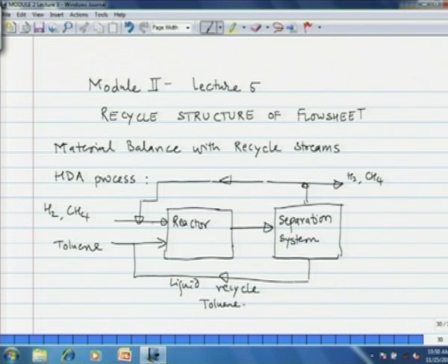Let Ft denote the total toluene feed to the reactor, out of which some part comes as a recycle stream and other as fresh stream. So, the fresh toluene that is fed to the reactor is denoted by FFT. And now we try to do material balance for a certain production rate of benzene and also diphenyl as a side product.